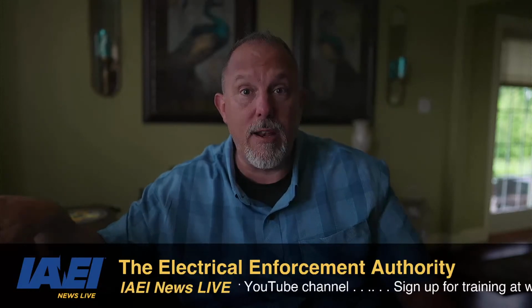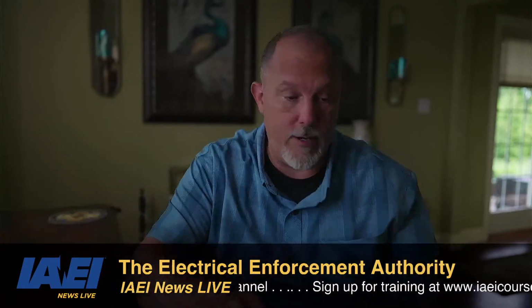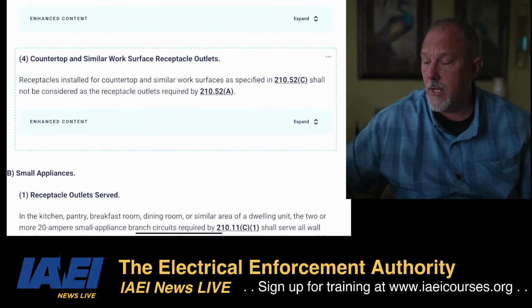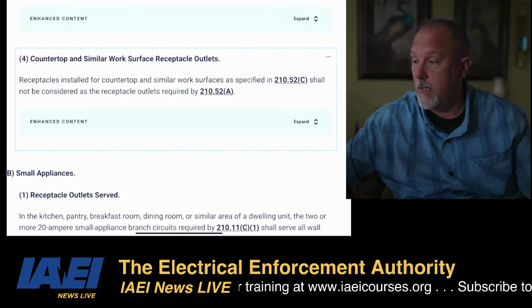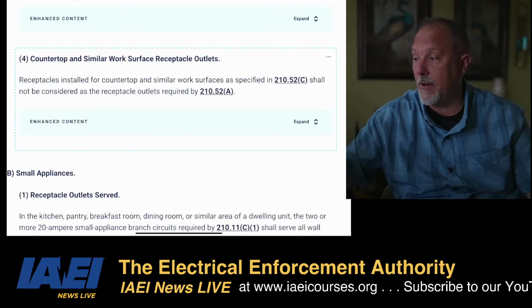How do you not think? I'm just reading the words. Here, I'll put it on the screen. It says it right here. Receptacles installed for countertop and similar work surfaces as specified in C shall not be considered as the receptacle outlets required by A.